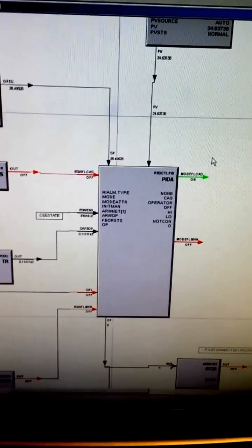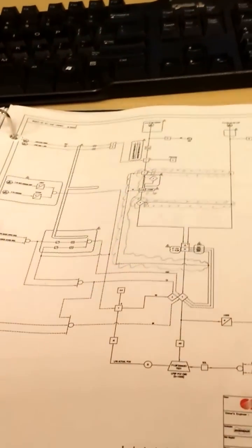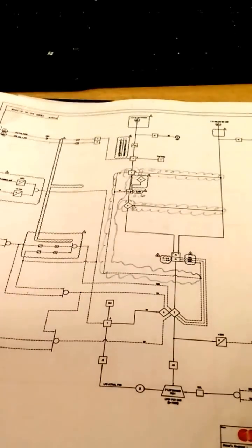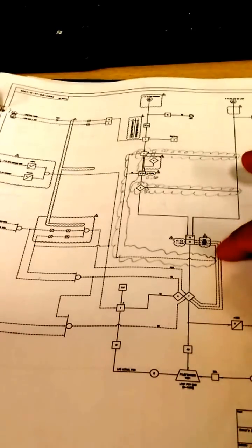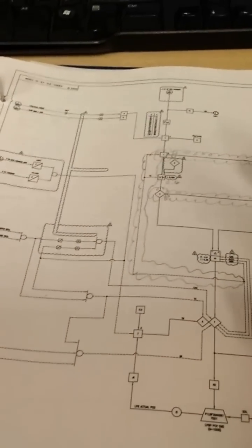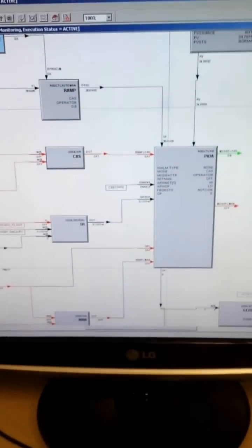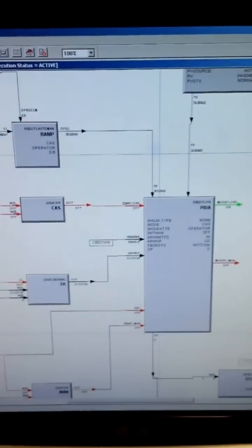Now what I'm going to emphasize here is the comparison between this implemented logic in the DCS and the control loop. So what is the difference? Basically the logic is the same, but only the drawing. This one is using the SAMA symbol or the sketch for SAMA symbols, and this one is a function block. This is now the actual logic.